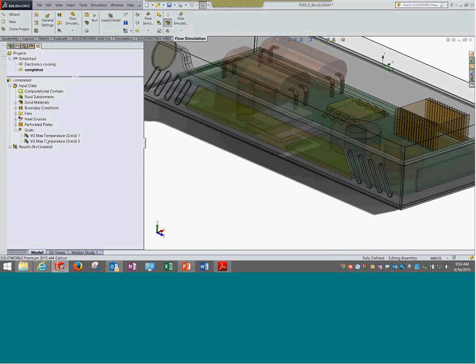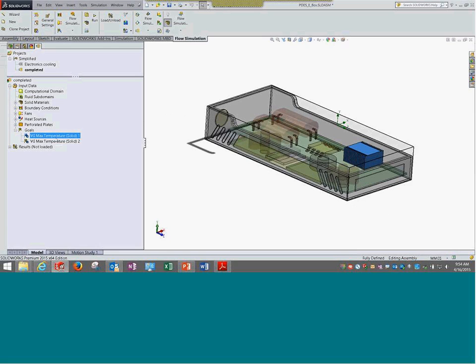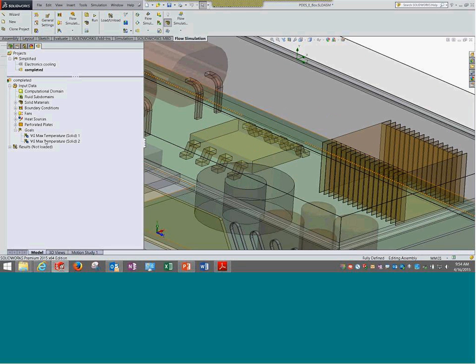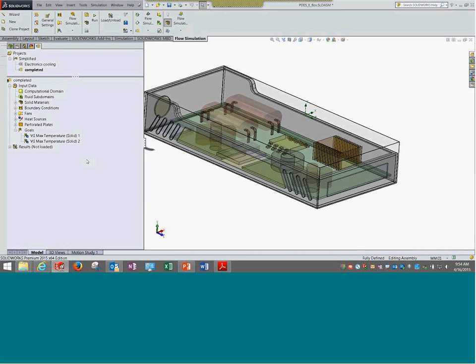In terms of goals, as we discussed yesterday, of course, all other goals are converged, but the goals which are most important or which you want to monitor here probably could be these two. So there is a chip which is generating the heat and is supposed to be maintained at a certain temperature. If it goes above, I don't want to let it go above that and have it working efficiently. And there is a heat sink which is dissipating the heat from the system. So only these two probably are the ones which I want to monitor, understand, and do accurate analysis, so I get accurate values. So I kept them as goals. It doesn't mean that other goals are not converged. All are converged.